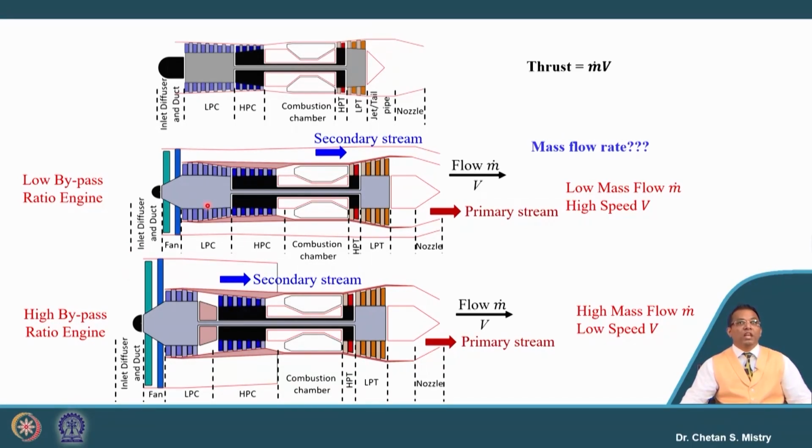Okay. So, what was the limitation here for the turbojet engine? Let us discuss that. The major concern is, in order to handle a large mass flow rate, you need to have larger dimensions, that is what we are providing here also. But the thing is, by having that large mass flow rate, we are not able to achieve higher thrust, because my exhaust velocity will not reach the number we are looking for.